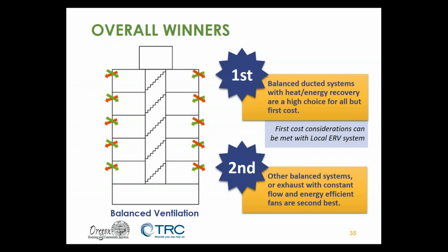Second choice, other balanced systems, or possibly exhaust with a constant flow, and making sure that you are installing those with energy efficient fans and proper considerations of static pressure loss if they're ducted, really engineering them appropriately and having a constant flow.